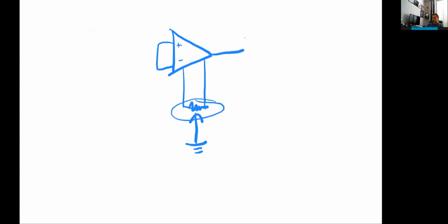So basically, you would have some type of port here, and you would tie the inputs together, and you would dial this variable resistor until the output is 0, and that nullifies that offset. But as a 3-terminal device, you will always have an offset because it's dependent on the overdrive voltage.